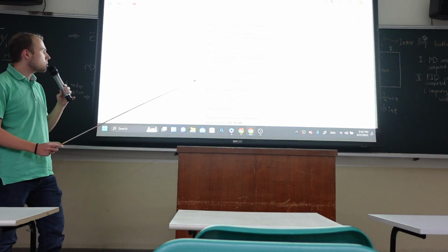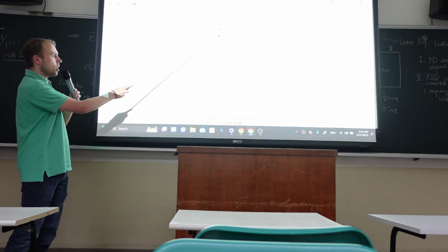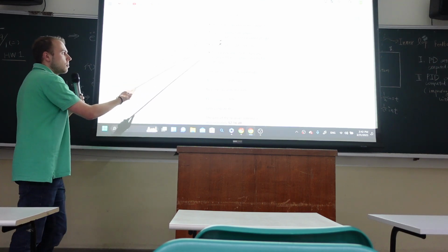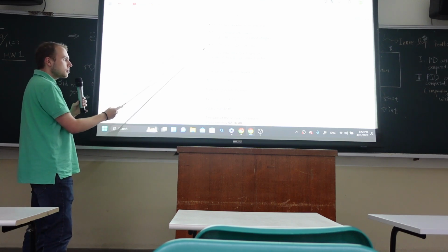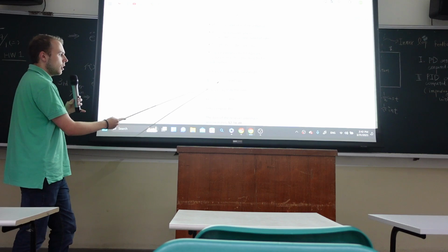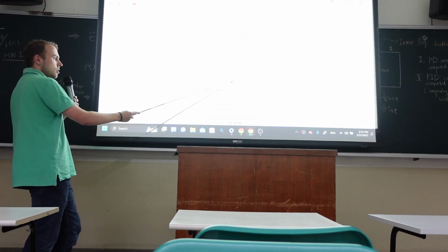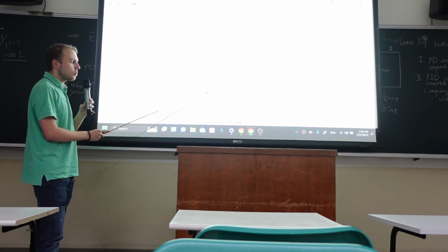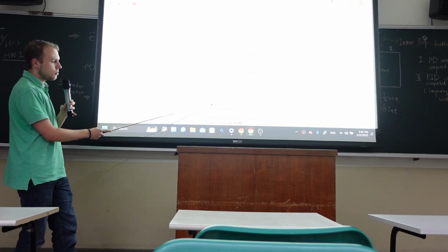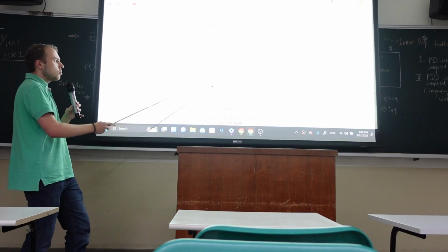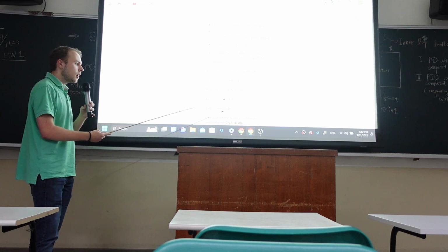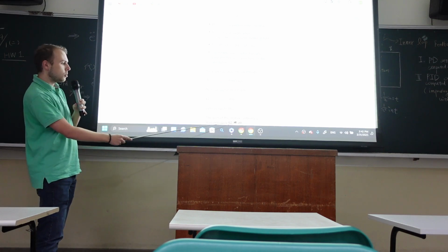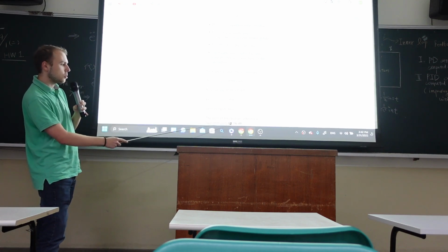Okay, so this is the first problem. We have the diameter of the antenna. We have to get the wavelength, and we can calculate it here. So we get 0.015 meters. And to calculate the gain, we use this formula and multiply it with 0.6. If you get it right, we get the result 52 decibels.